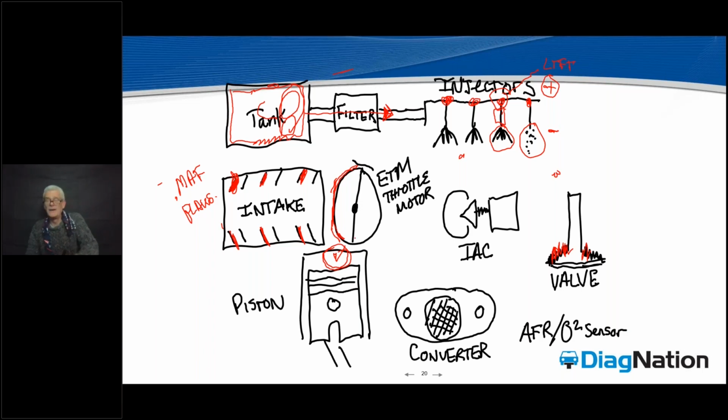Now, I want you to follow me over here, because I've got to see where my little tool is. Think about this. Let's just say my injectors, baseline, clean and new car, were at 1.5 milliseconds at idle. Warm idle, unloaded, no headlights, just warm idle, unloaded. That's where you want to do this test.